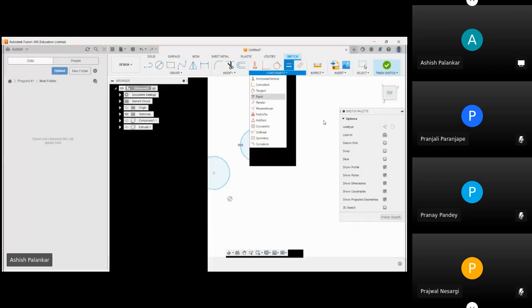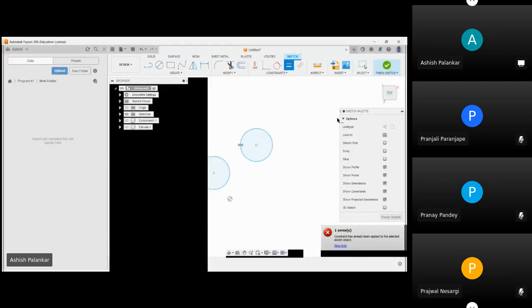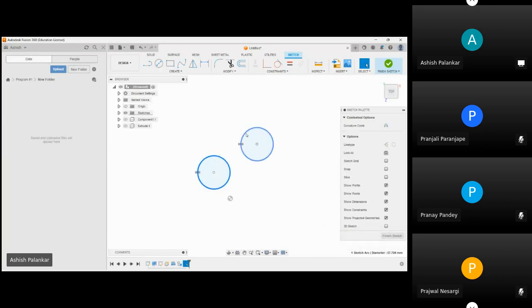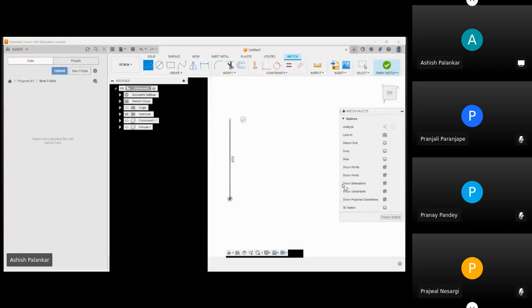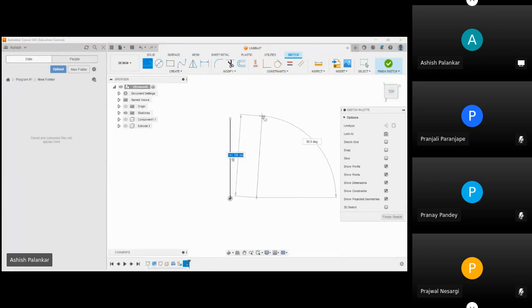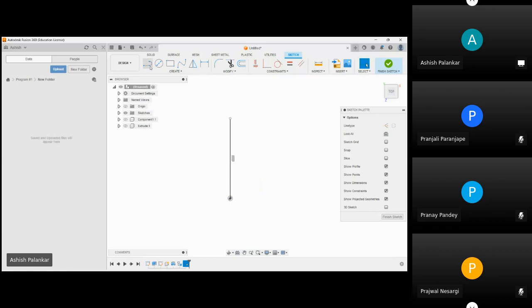And let's go to parallel. Select this, press Control and select these two circles. Oh, I have to unselect the constraint. Unselect the constraint by pressing Escape on your keyboard. Select this circle, press Control and select this other circle, and press Delete on your keyboard to delete the sketch. About parallel, you can see if I create a line, press Escape, and create another line, escape. Now you can see you cannot give parallel, right? The constraint makes two lines extend in the same direction, but these two are not in the same direction. So you can undo this, delete, and give another line, escape.